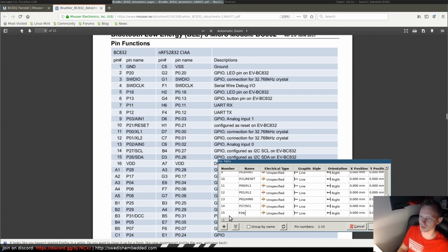And once I'm done with both the symbol and the footprint, I'll just go over it quickly, make sure all the numbers are correct, and then once the schematic is done, I go through all the components in more detail and actually check all the electrical levels on each pin, which would be sort of the final review of this component before it can be marked as verified. Let's see, SDA